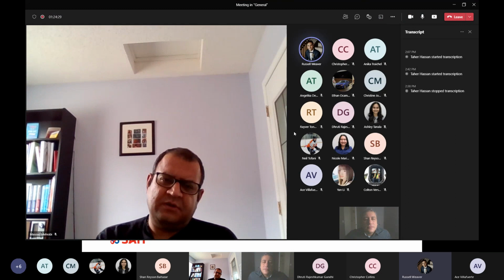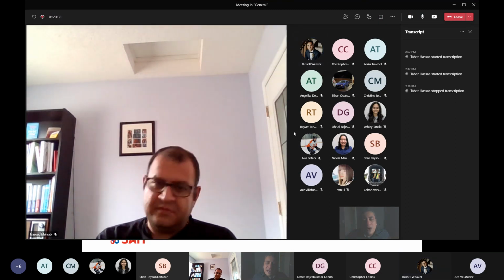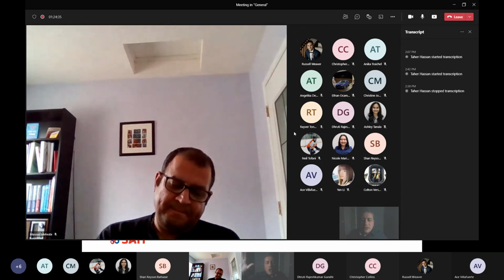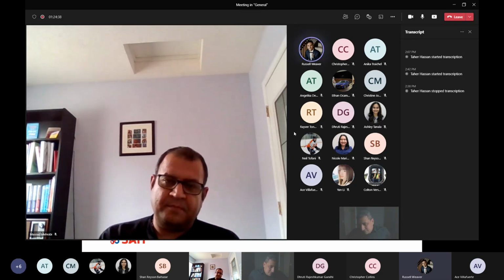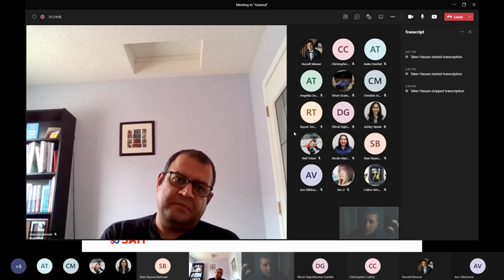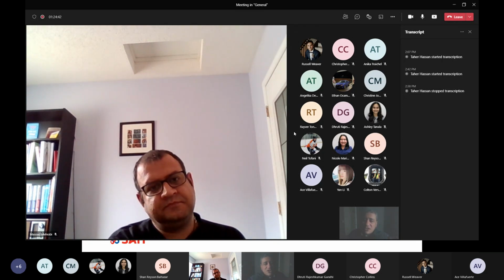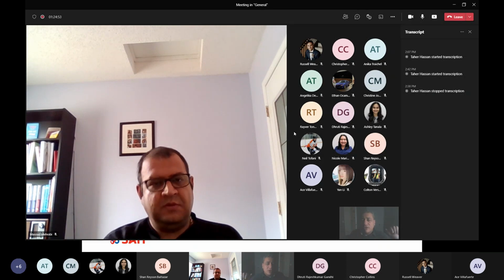Probably just part of it, correct? Just part of it. Why is that, Russell? Can you tell everyone why we're able to only establish part of it, not all of it? Because you need more data points. Because I have removed the extensometer, which measured the strain. Remember, there is one variable. As soon as we remove the extensometer, it means one parameter cannot be measured. So we measured slightly after the yield, and then we removed it.